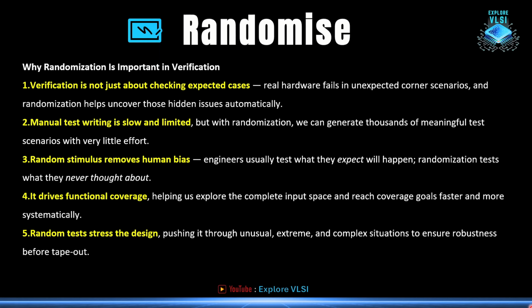So let's get in. What is randomization and why is it so important? Randomization in SystemVerilog is a very important feature. We can't write the data manually like we do in the Verilog test bench. Why? Because as designs become complex, we need to randomize the data and touch upon all the corner cases of the DUT functionality. Verification is not just about checking the expected cases. You might have expected some cases of the functionality in the DUT, but there are other cases that need to be checked, which may or may not seem important. We need to check all the small cases as well. That's why randomization is very important.